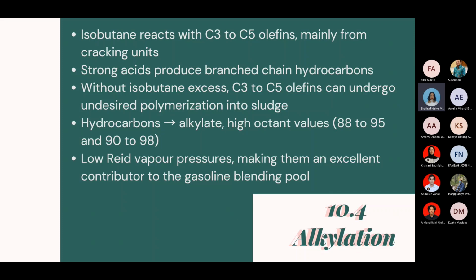Now, these hydrocarbons, famously known as alkylate, have a high octane value, 88 to 95 and 90 to 98, and low Reid vapor pressures, making them an excellent contributor to the gasoline blending pool. Next.